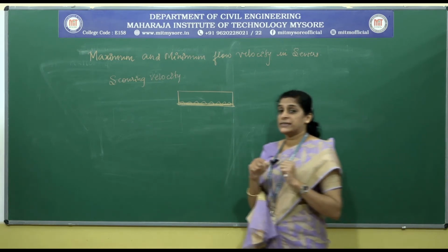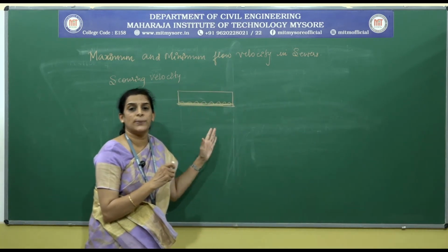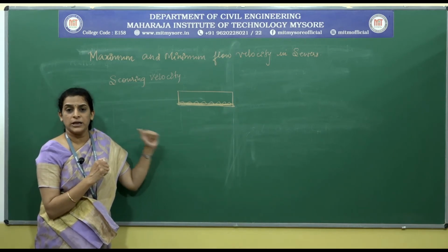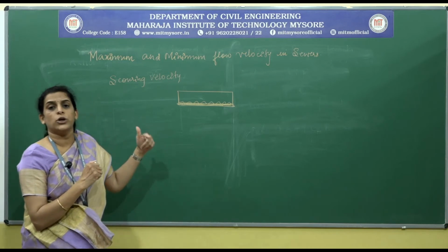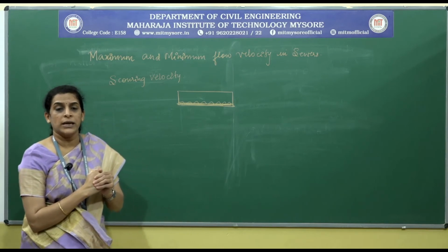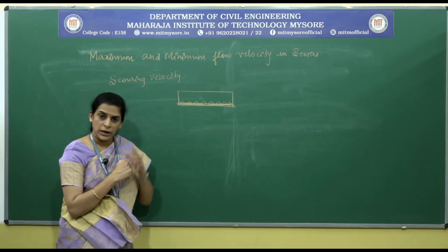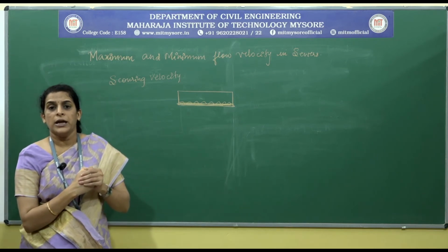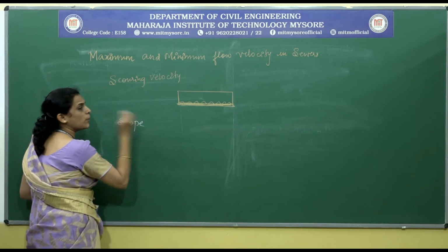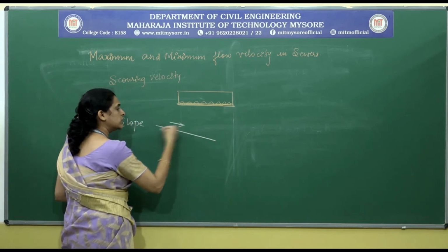Why is the velocity a concern here? Because if the velocity is not selected suitably, then it hampers the gradient, which in turn causes deterioration or lessening of the efficiency, thereby causing hindrance for the passage of the sewage. Or otherwise, in one more sense, if the gradient is not proper, that is, if the slope is not properly selected, it causes